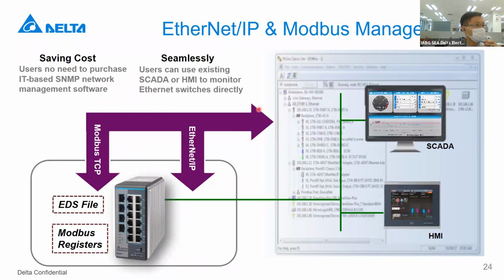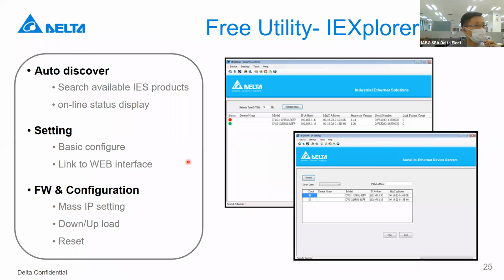And this is the Modbus management if you have SCADA and HMI. I think it's very easy to manage the Ethernet switch, because it also supports Modbus. So you can regard this one like a Modbus slave to do some settings. And also we do have the software.